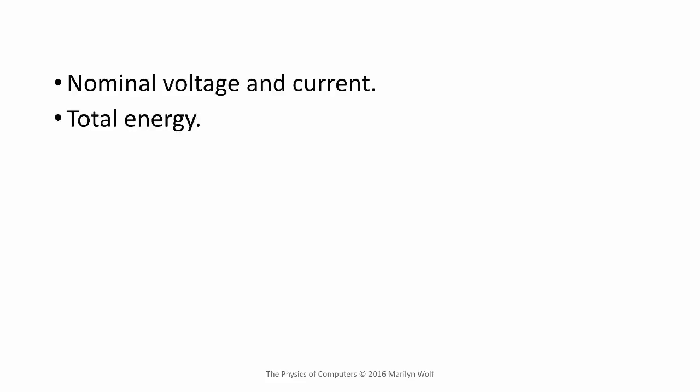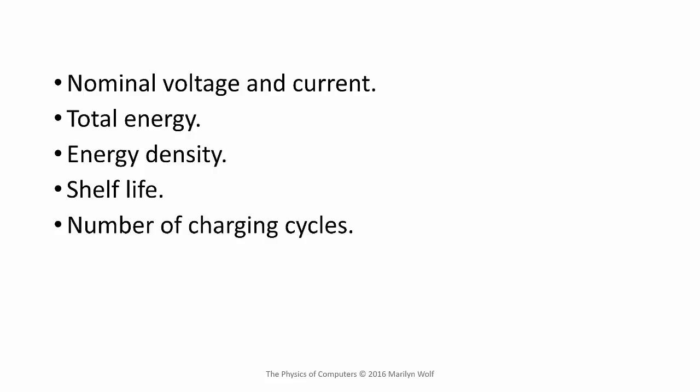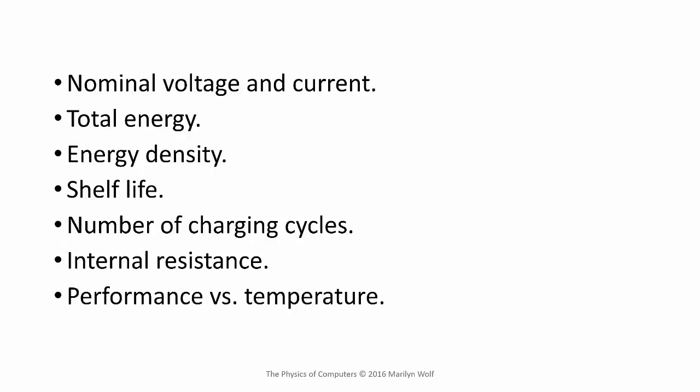We have nominal voltage and current, total energy, energy density, shelf life, how long we can leave the battery before it goes bad, the number of charging cycles before it stops taking a charge, internal resistance, performance versus temperature, and a number of other characteristics.